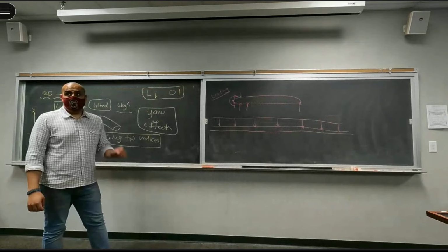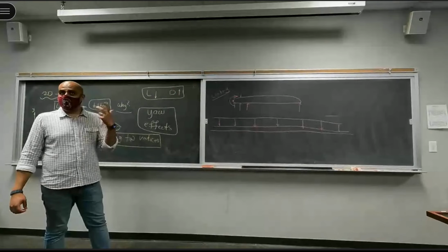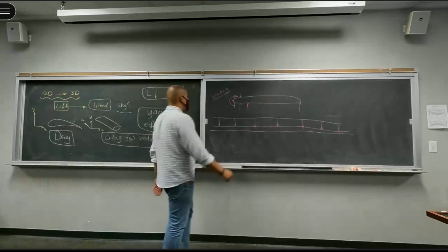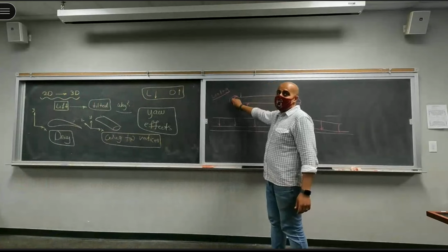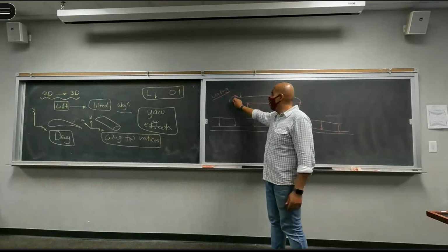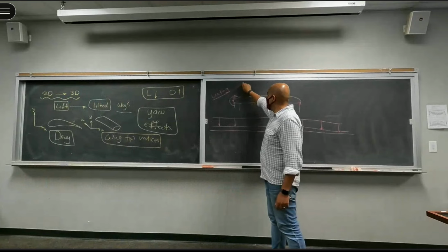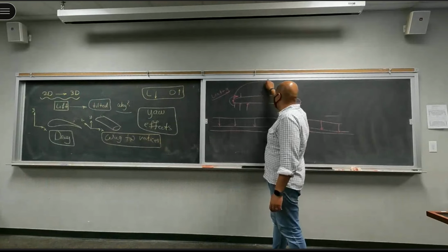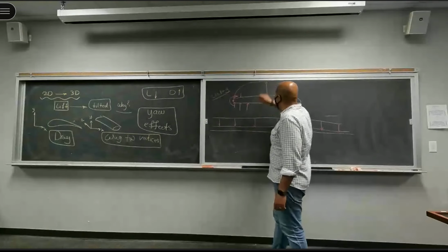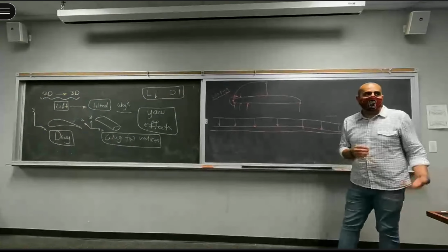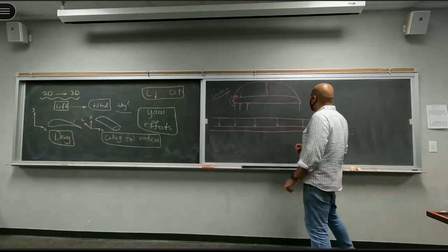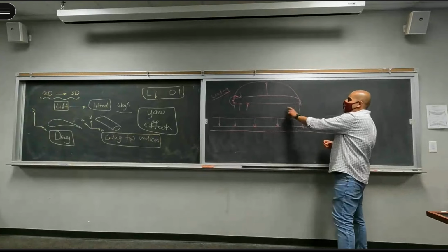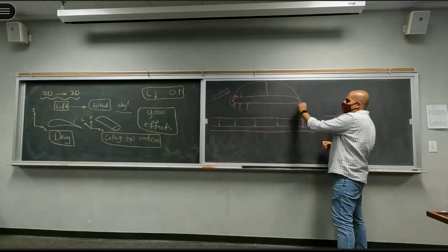But on a real wing, on a three-dimensional wing, since the pressure difference here is zero, your lift at the tip is going to be zero, right? So you will see the highest lift at the middle or on top of the fuselage, then it will go back down to zero, right? It's because of this flow leaking from bottom to the top.